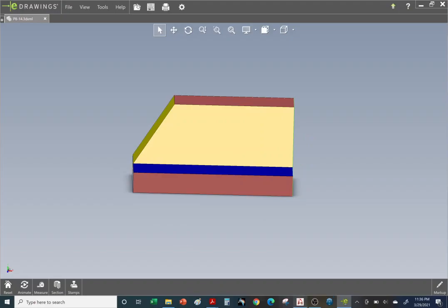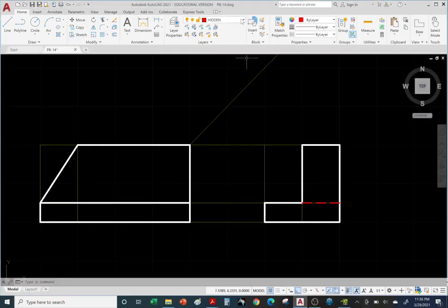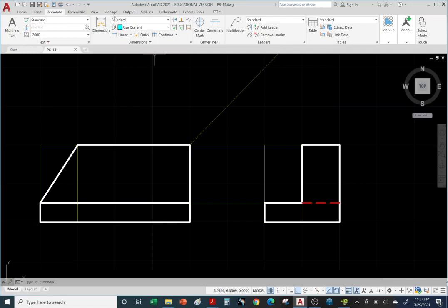All right, so let's go back to AutoCAD. Let's go to the dimensions layer. Okay, so let's go to dimension. Now we can stay here on the home tab and use the annotation panel. We have a little bit of annotations and dimensions. It's limited, but if you want the full-blown dimensioning and annotations panels, go to the Annotate tab. You have a lot more options. So you can see we have more options for dimensions and notes, for example.